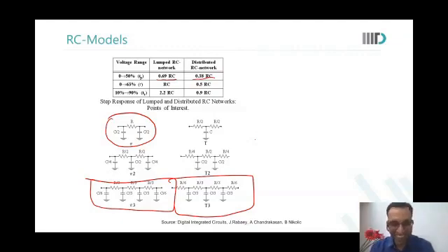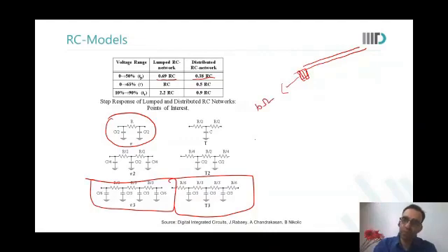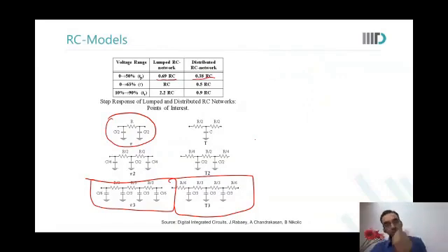People do not understand this. The thing is that the length of the current flow through a via is not in your control, is it? When I make a wire, I can decide how long or short to make it. But for a via, you have no control over the depth. This is defined by the process. So whenever we put a via, we say this via has a resistance of, let us say, 10 ohms. If I cannot afford 10 ohms, I will put 2 vias. The effective resistance will be 5. With 3 or 4 vias, I can reduce the overall resistance. In a wire, you can reduce resistance by making it wider, but with vias you can't. Therefore, the resistance of vias is given separately, and because it is given separately, the tool understands it as a separate wire.